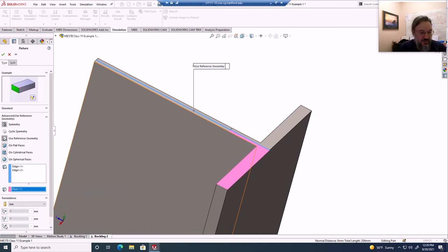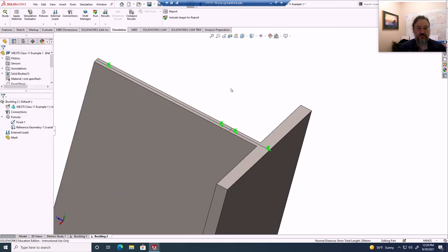Okay, and I wanted to let it go up and down. So the one that shows it as perpendicular, which is this bottom one here, you can't quite see it maybe, but you can see these other radio buttons. I'm going to go this way, so it's not going to let it go in the Z direction, and I'm not going to let it go this way, so it's not going to allow it to go in the X direction, but it can go in the Y direction. All right, so that's an important thing.